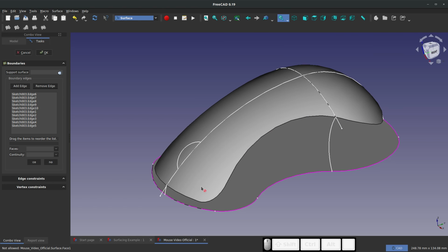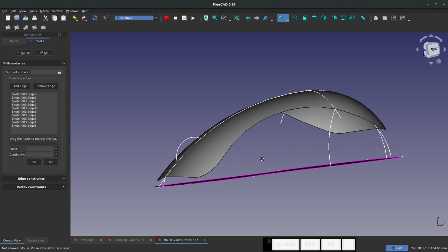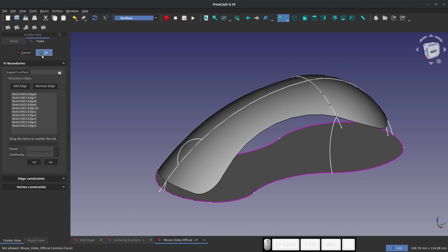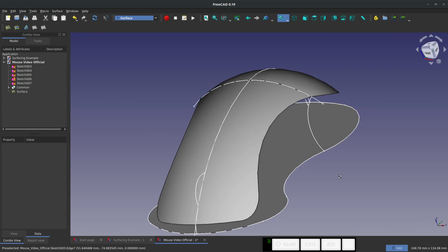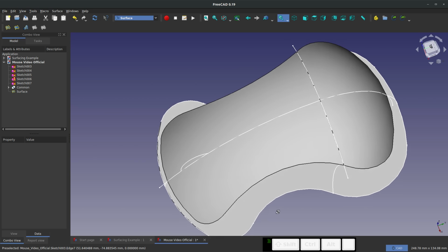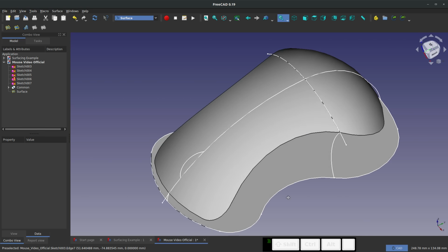And when I choose close barrier, you can see that this shows up. So I can make a surface for the bottom of the mouse, right? And that's where I got in a little bit of trouble because I went a little bit eccentric out here. Nonetheless, when we just wish to make a surface from a bunch of boundaries, we can use this tool.